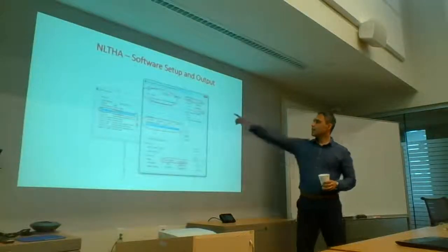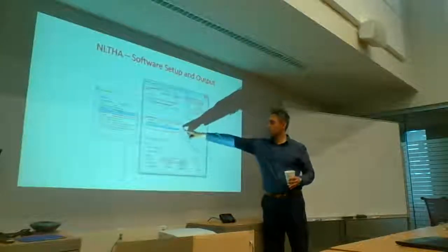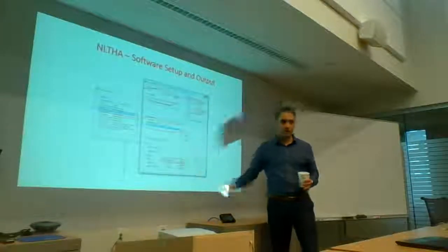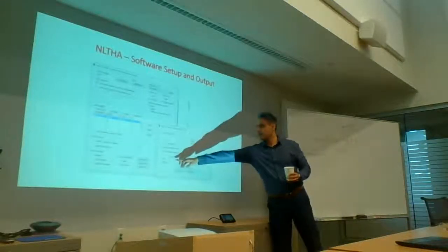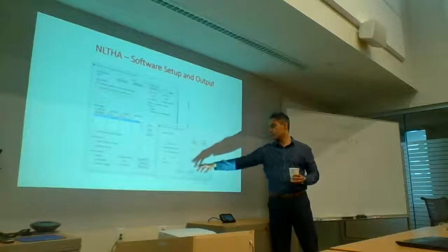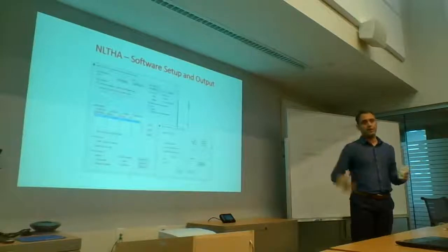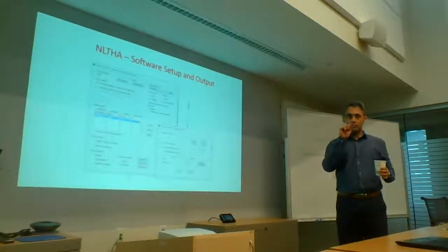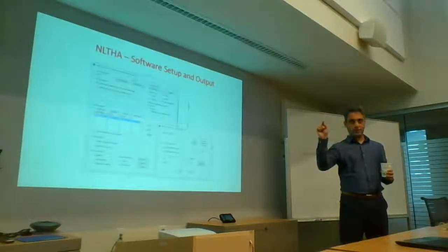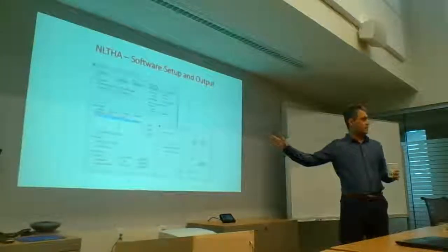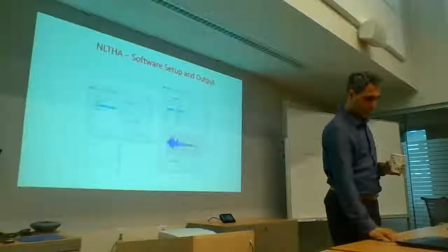So I say use 0 initial conditions, use direct integration, use time history. I've got proportional damping here. And when I go to proportional damping, I say my first modal period and 0.1, and 1, they're at like 99% damped. They're just heavily damped. So you won't have any of those effects. The reason I'm not starting my time history until after 20 seconds is I want any kind of damping or vibration to have completely died out. And I'm putting in a lot of damping in there.